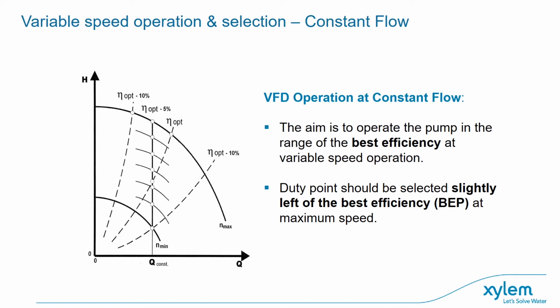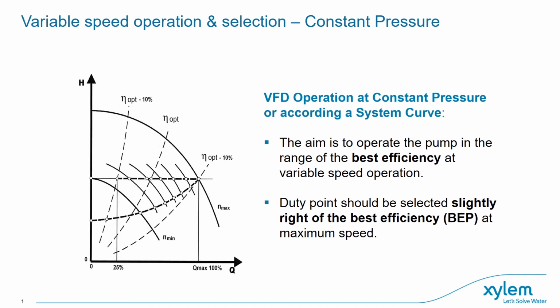So if you have something like a washdown system where you had multiple guns but needed to give a constant flow, then this is where you would need to increase the pressure to cope with the increased friction loss through the system. But you would just say, okay, I'm set to this constant flow and I need to ensure at the furthest point this is the flow I'm getting. So it would just increase or decrease in speed accordingly to overcome the friction losses within the system.